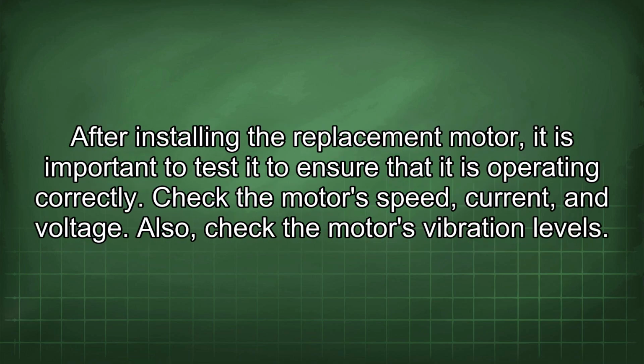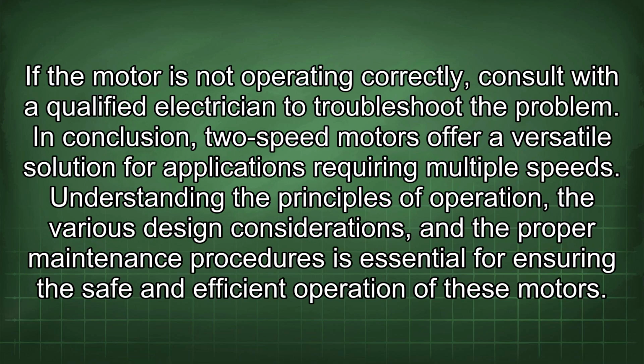After installing the replacement motor, it is important to test it to ensure that it is operating correctly. Check the motor's speed, current, and voltage. Also, check the motor's vibration levels. If the motor is not operating correctly, consult with a qualified electrician to troubleshoot the problem.